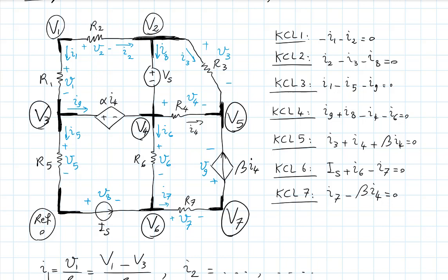Okay, so when you work on your assignment, for now I very strongly urge you to start by writing your KCLs in this form and then replacing things in terms of node voltages as much as you can and proceeding, rather than trying to recognize the patterns and input them from the beginning. Okay, because this is really how you need to practice to develop the insight and skill, and then gradually you will be able to do it faster. So this is the essence of nodal analysis.